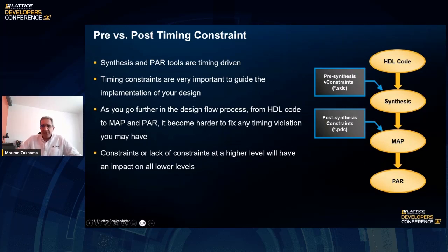Pre-synthesis constraints are entered at the synthesis level, so they are an input to the synthesis tool. Usually it's an SDC file, and the post-synthesis timing constraint is a PDC file. They are very important to guide the tool. You can think of the synthesis tool and place and route as algorithms that have an objective, and the objective is meeting the timing. So they will guide the tool to prioritize things so it can implement the design to meet your target timing constraints.